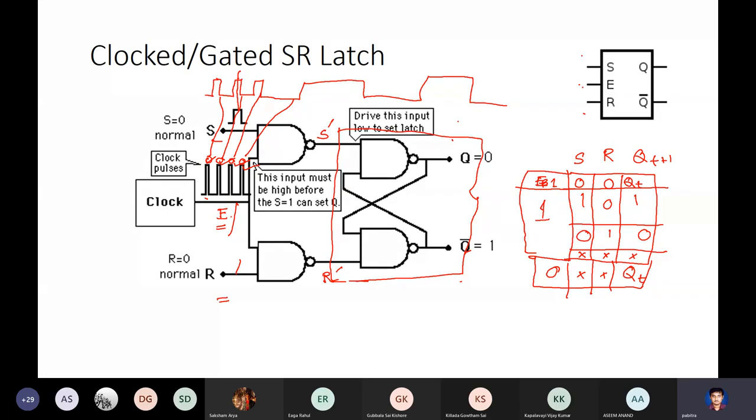they are all going to have the clock pulse high at the same time, which means that they are going to respond to the input, and so their outputs are also going to be changing only at that same time, and they will respond to the value of the input also at the same time. All of them will respond to the value of the input at that snapshot in time at which the high of the clock pulse happens.